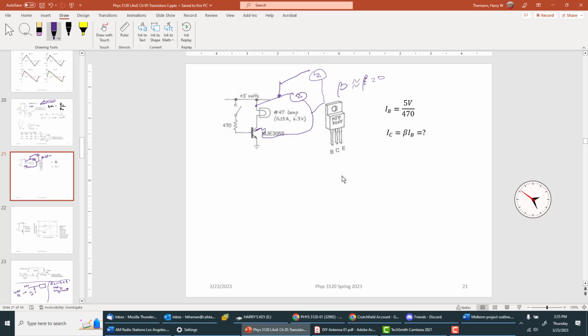So it has a certain resistance, and if I change the voltage, it changes the current, huh? So what's happening here, they're in parallel, so I get the sum of these two currents. Now, in a battery, because of the internal resistance, slowly but surely, as I increased the amount of current flow, the voltage would go down, right? And remember, this is really a direct short, almost.